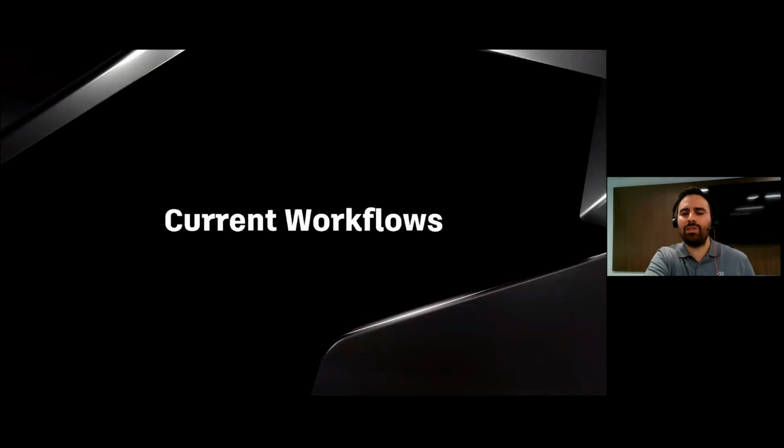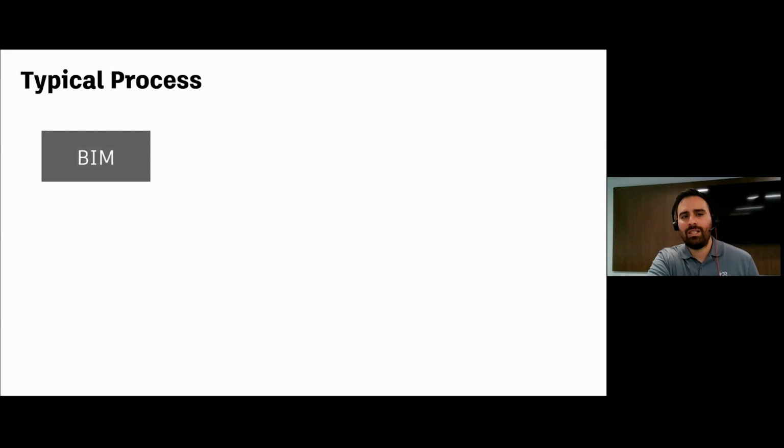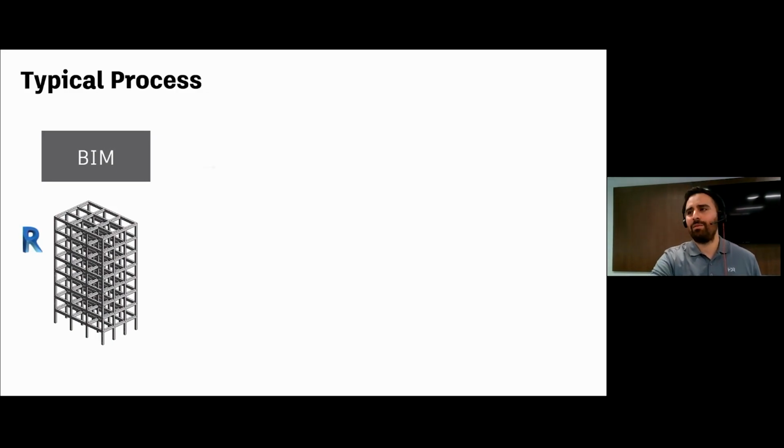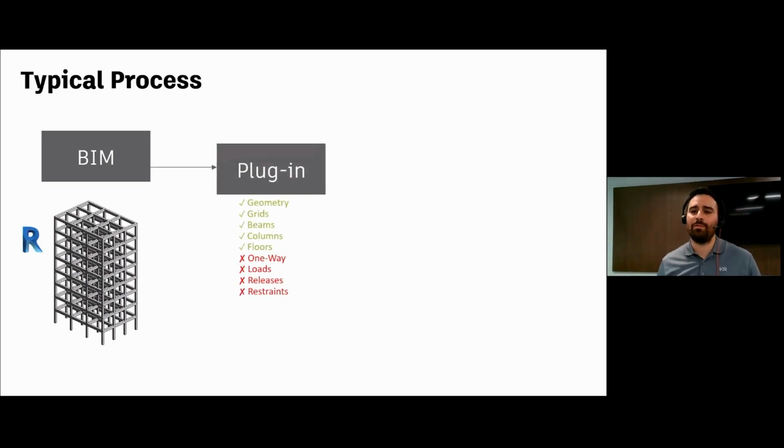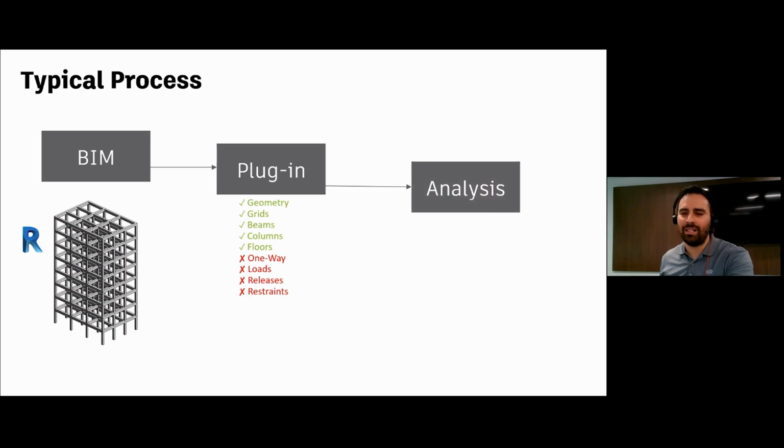So we're first going to look at our current workflows. We're going to start with what most structural engineers work on day-to-day. The typical process involves starting in BIM, usually Revit, but it can be other things. From here, we go into some type of plugin. This plugin could be many. It doesn't translate everything, but it translates some things, which is somewhat helpful. From there, we go to analysis.